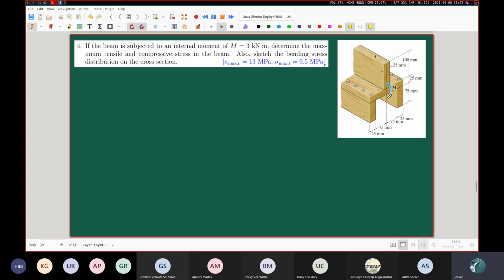So in that sense, the solution of this problem and the calculations involved therein can be kind of modulated. Okay, it can be broken down into modules which you are quite confident about individually. So once you have done a few problems and tested out your script for the T-beam, you know that it works and you can just put in the values here. With reference to this kind of a base, you can calculate the centroidal axis, and then with respect to that base, finding out the centroidal axis of these two things are also quite easy. So things can be broken down in a very nice fashion. Okay, you can have more complicated situations like this also.